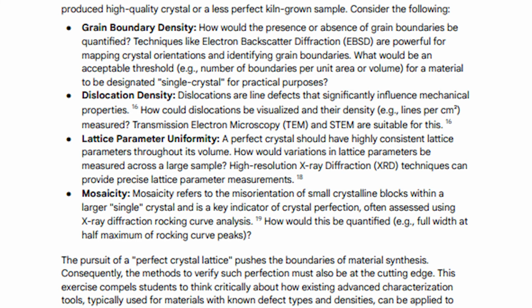Lattice parameter uniformity. A perfect crystal should have highly consistent lattice parameters throughout its volume. How would variations in lattice parameters be measured across a large sample? High-resolution X-ray diffraction, XRD techniques, can provide precise lattice parameter measurements.